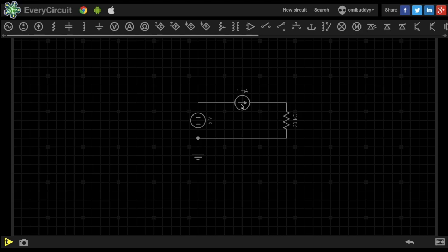In this case, there will be no effect of the current source on the output voltage, because the output voltage itself is the input voltage and it cannot change regardless of whatever amount of current the current source wants to provide. So the two cases we had analyzed, which are putting a voltage source and a current source in series with the load resistance, are the only two possible cases which we can use to get gain out of this circuit.